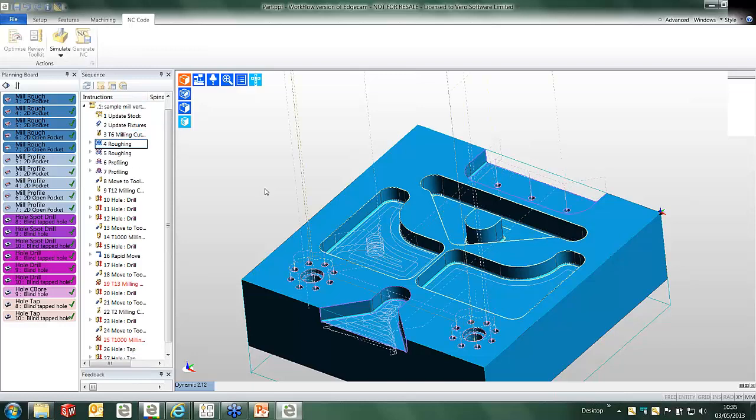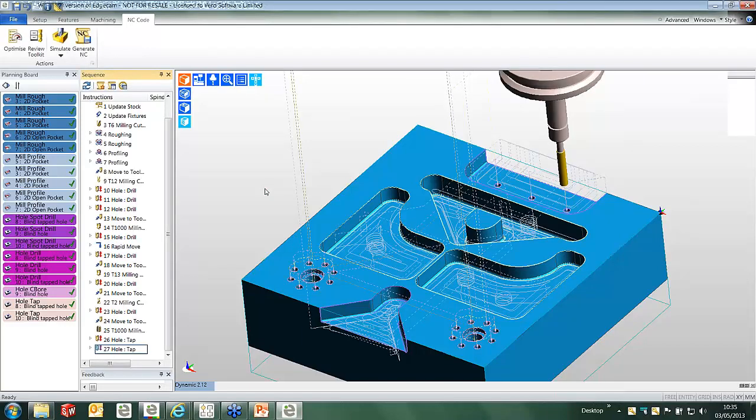And this gives us 2 benefits. First and foremost, it will give optimized cycle time. The passage between the pockets will now be considered and the shortest route taken. This will obviously give us good cycle time reduction. The second benefit is that the sequence will be reduced. So on a more complex shape, we'd anticipate around a 30-40% sequence reduction.